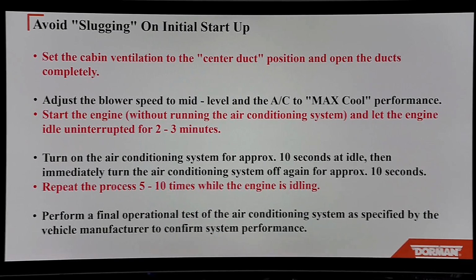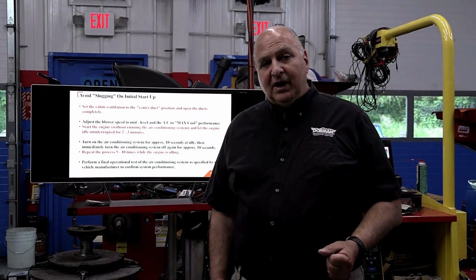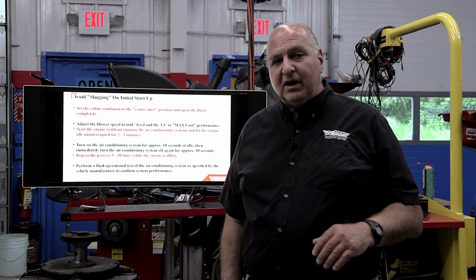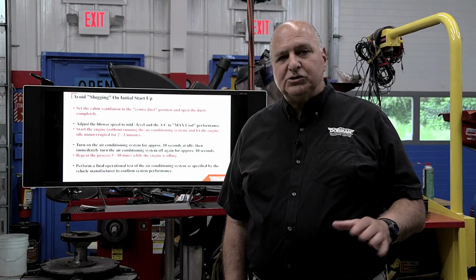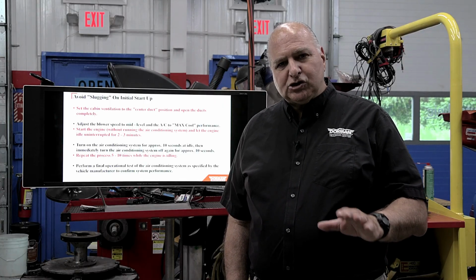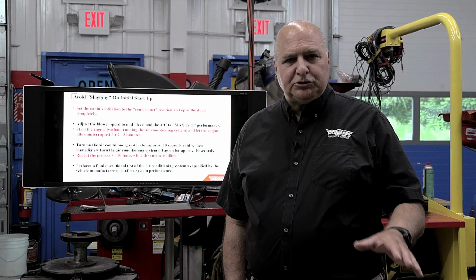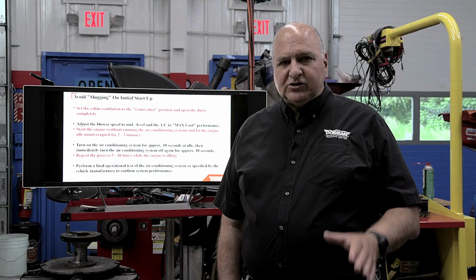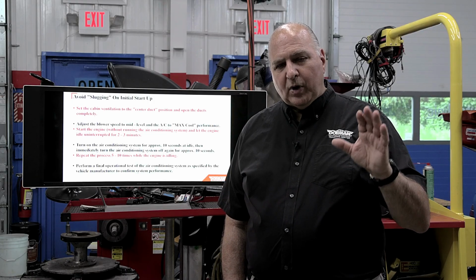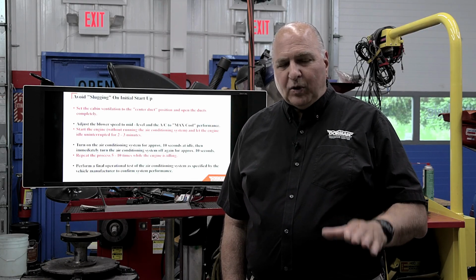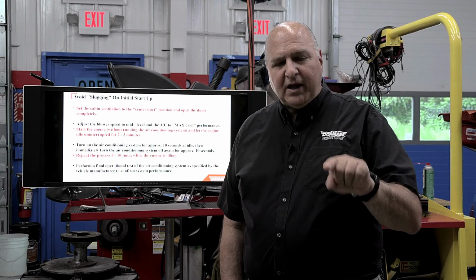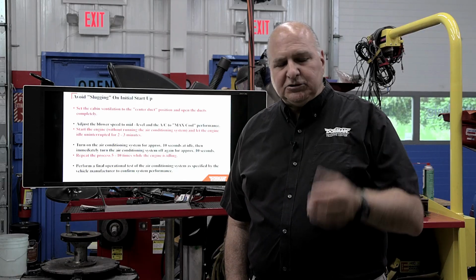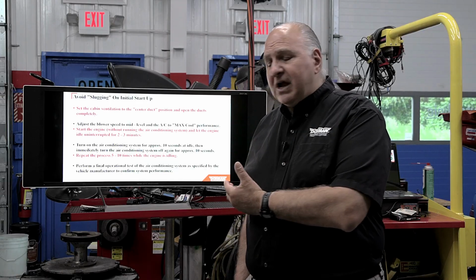So you know what this is like? I just got my Vette out after a year of sitting, okay? Because I couldn't see, like I told you, I had a bad left eye. Pretty dangerous driving, so I wasn't driving. At any rate, when I go to start it up, because it's been sitting there, and it's a supercharged version, I want to get the oil going through. Same with turbos, okay? I have a CTS-V, and when I shut it down, I let it idle for a bit. When I change oil in it, I'm going to crank it over, hit the start button, shut it down, start it up, shut it down until the gauge pressure comes up. Basically, you're doing the same thing here.